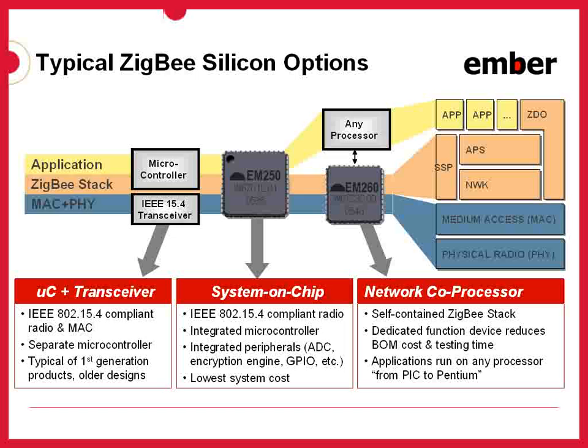Generally, the microcontroller combines the application code with the stack code to produce a monolithic binary that runs on that external microcontroller. However, due to the complexities of porting the stack to different architectures and getting a driver in place to tightly couple the RFIC's operation to what's happening at the stack processor, this model is not considered very portable across various microcontrollers, with stack vendors often limiting their offering in this area to only one or two specific MCUs.